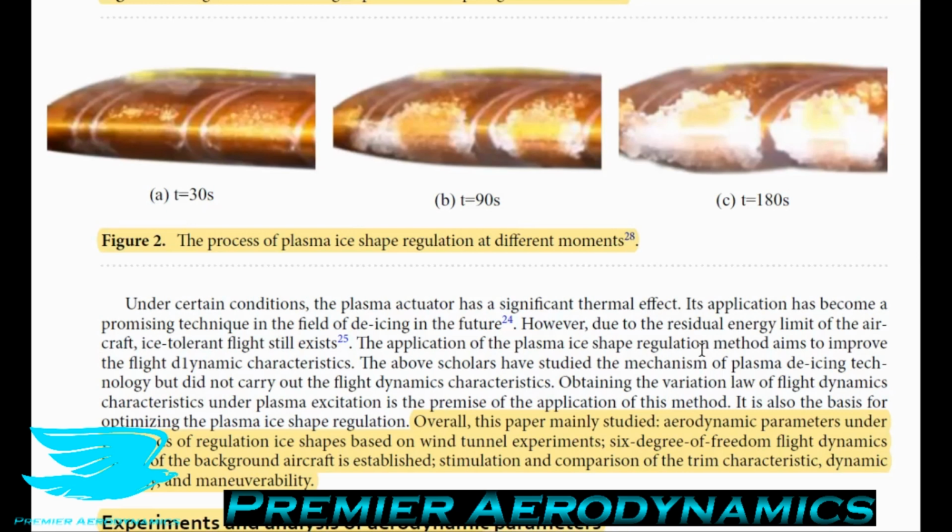The main benefit of tubercles is that when you pitch them at non-zero angles of attack, they start to produce leading edge vortices. So very similar to vortex generators. And these vortices can delay stall, and that's their major benefit. They do have other benefits, such as reducing drag under certain conditions and increasing lift under certain conditions. But generally speaking, it's just the stall characteristics. So they delay stall and they soften stall. Those are the 2 major draws. And these bumps look very, very similar.